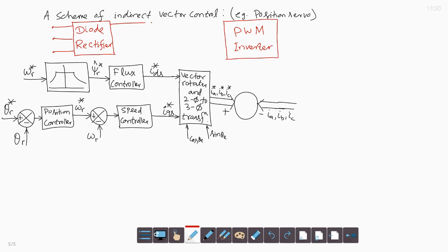The PWM inverter gets filtered DC supply from the diode rectifier. This is the capacitor filter CF which filters the ripples in the diode rectifier output. Then in this circuit a dynamic braking resistance is included. This is the braking resistance RB which gives dynamic braking.